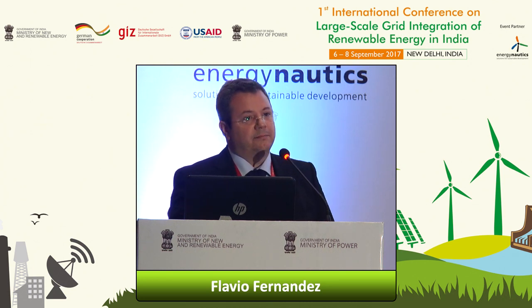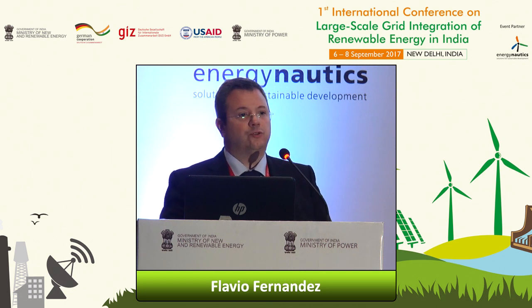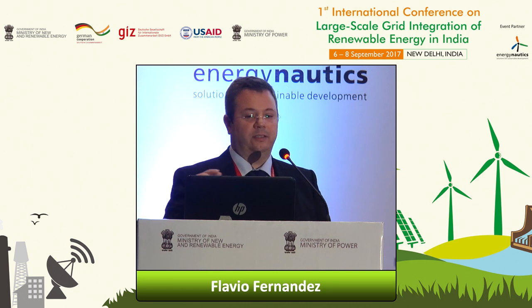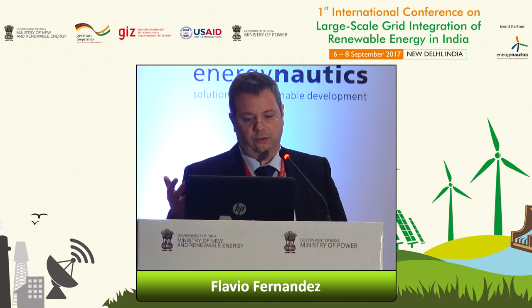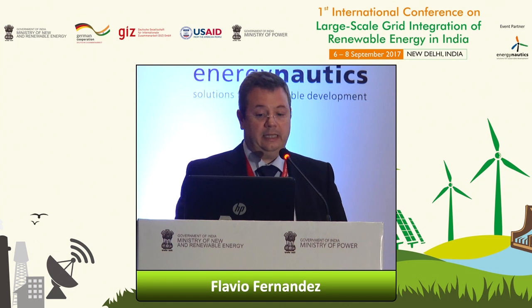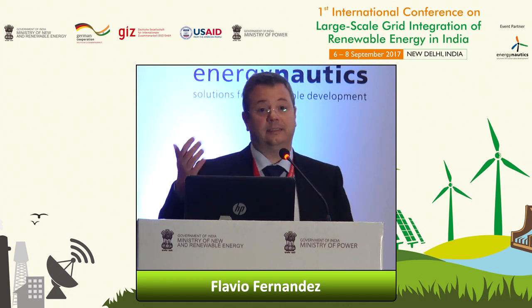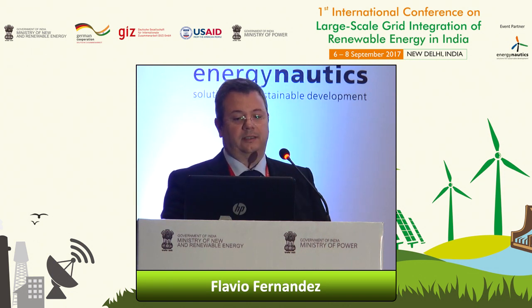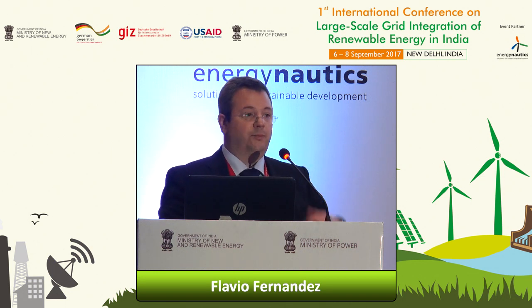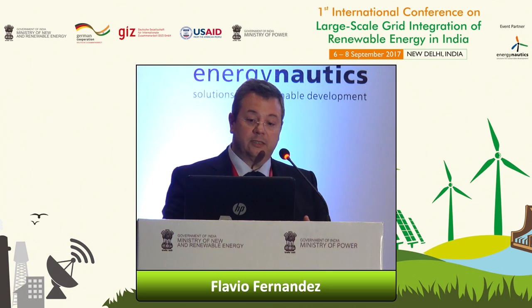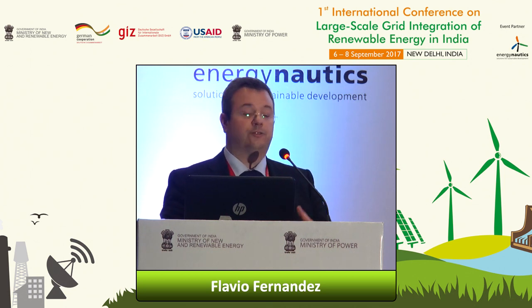Of course, you get some less detailed representation. This is true, but on the other side, it doesn't mean that the model is not fit for purpose. Depending on what you want to do, definitely it's not adequate for internal faults. But in most applications, we look at the impact of the model on the network. And the other thing is, at least the standards claim, the model can run for step sizes up to 10 milliseconds.